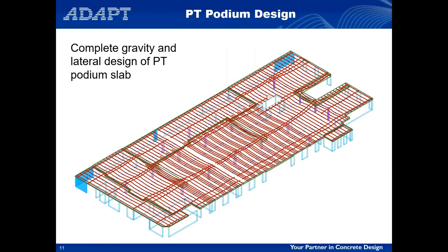Once we have our loads defined on the podium, the design of the podium itself is no different than any Floor Pro analysis and design that you've gone through. You're just running it in single level mode, laying out your post-tensioning, laying out your support lines and everything else.